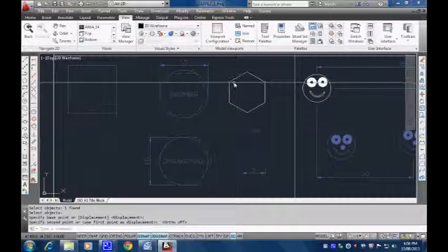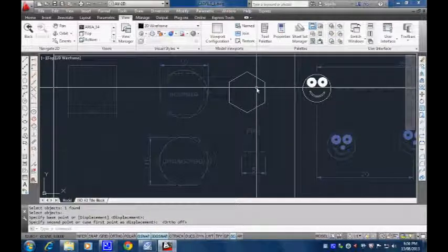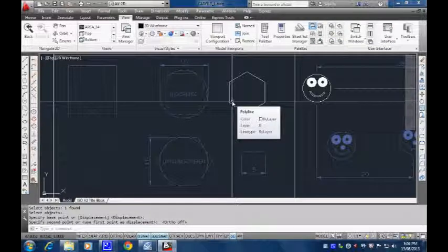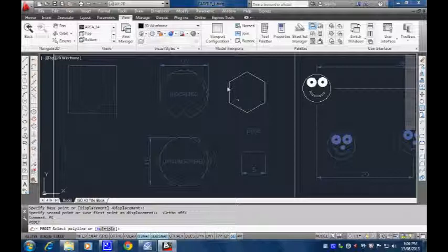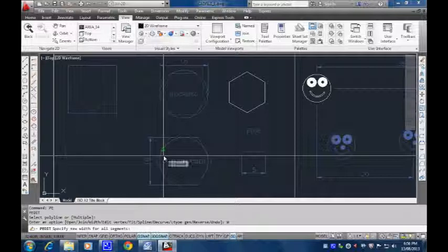Alright, so now the other thing it does, it gets you to change the width of this. I think you will be using a command called Polyline edit. Those of you who have done it, correct me if I'm wrong, but that's one way you can do it. And under Polyline edit, you get lots of different options. One of them is to set the width, W for width, enter or click it. Alright, what was it, 1 that it got you to do?